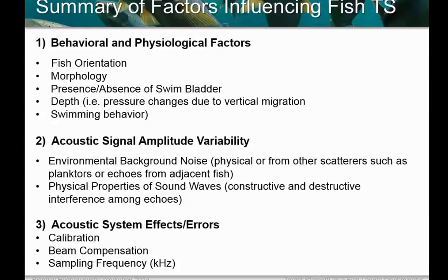We know this one, the variability in the amplitude of the signal, which target strength comes from. It's corrected for where the fish is in the beam by the split beam systems, but if we've got other scatterers, could be biological scatterers, fish in zooplankton layers, or noise from non-reverberant sources, like a generator that's getting amplified, that can contribute to that amplitude, and it can be either additive or destructive, depending how the wavelengths line up. So that'll increase your target strength variability. That's that second piece.